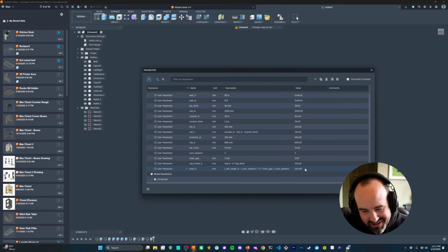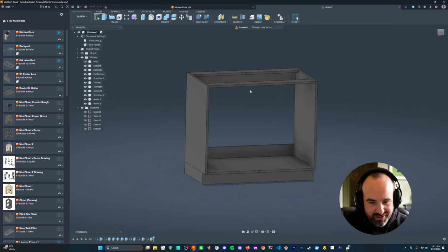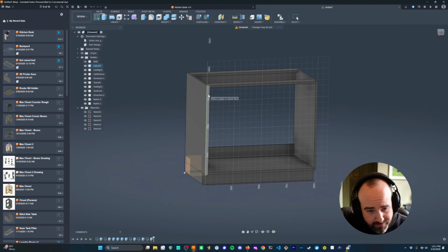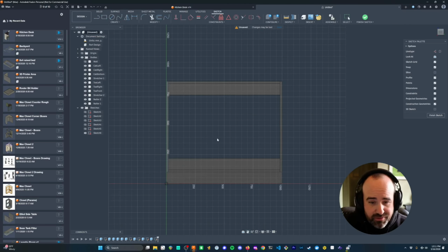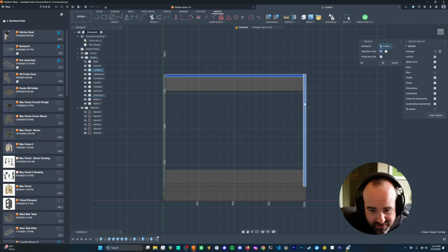When you're going to cut this stuff, it's impossible to measure these fractional units. You can round down. It's not a big deal. You're missing 0.5 millimeter. You'll never notice it. So now we know the height of the drawer fronts. We need to actually lay them out here. I'm going to create a new sketch, using the front of the box as the plane. Before I do any of that, I'm going to project all these sides so I have access to them.